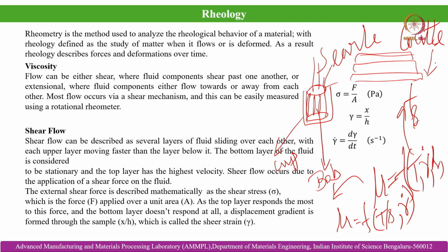In that case the same geometry is used, however, the cup is rotating, and the inner bob, which is generally grooved to facilitate shear, is fixed. Based on these differences, but with the same purpose, we differentiate rheometers or viscometers as Searle or Couette type.